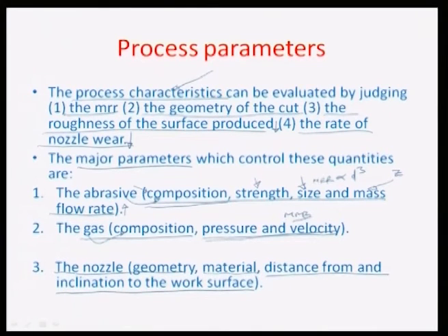So, when you are trying to create a small crevice or a hole in a material, what is important is the standoff distance, or the nozzle tip distance, NTD, because the MRR would vary as per this distance, and also the inclination at which the nozzle is placed with respect to the work surface. And for example, in some cases where holes need to be etched in an inclined manner, this would be the best process available for creating such micro holes and micro features within materials, particularly from MEMS aspects.